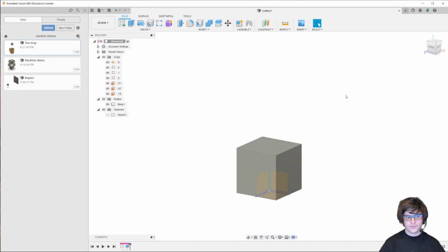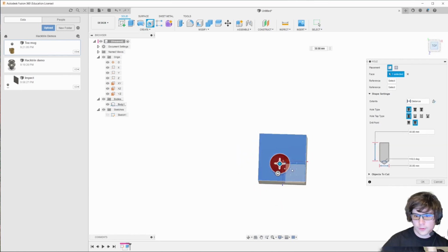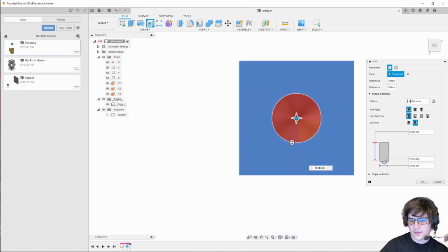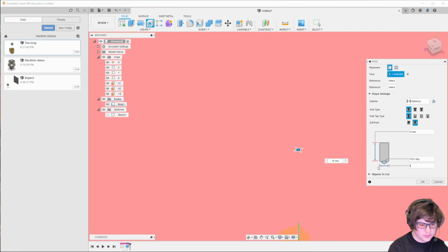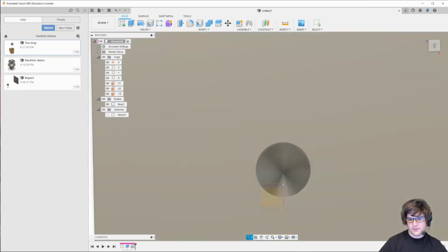So, after making a cube, you're wondering, what if I want to add some screw holes to it? You'll see there's this hole tool, which isn't actually that great because it doesn't really control where you put the hole. It just plops it wherever you click, and it's not very dimensionally accurate. But one thing that's nice is you can quickly add a hole. I want it to be 10 millimeters wide and 10 millimeters deep. And then you can have a chamfer at the bottom and so on. It's kind of nice.